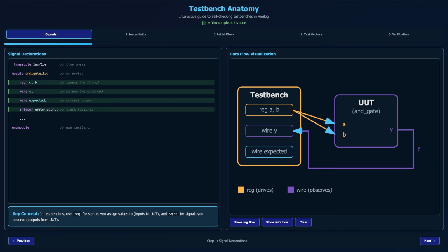Now, when students first start writing test benches, they often treat them like a one-off: let's just go through a few inputs, see what happens. But really, you need a more systematic way. As designs get more complex, the approach breaks down pretty quickly. If you're relying on just a few test inputs and looking at the waveforms, you definitely want to get away from that for more complex designs, where you can do automatic verification rather than having to manually check things every time.